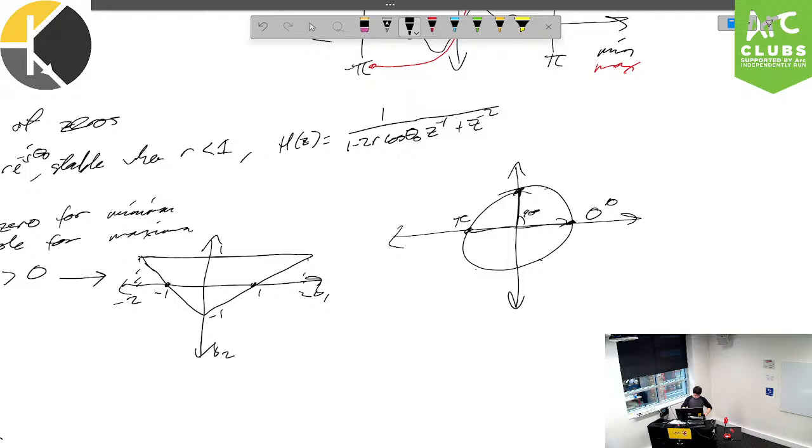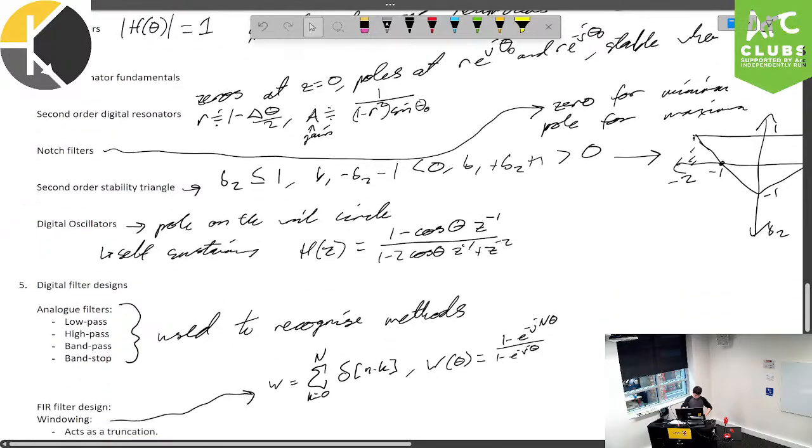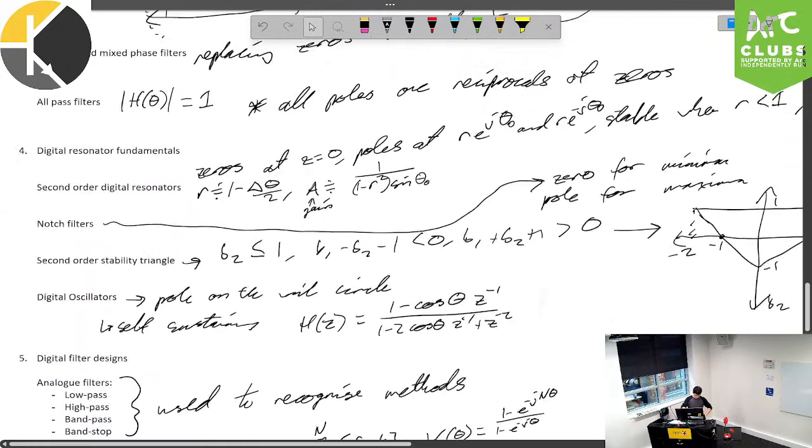And so, by having a 0 at 0, so I'll put an open circle there, by having 0 at 0, you effectively enforce a 0 action against all frequencies, if that makes sense. Because zeros try to pull it downwards, okay, to give you minimum. Whereas a pole tries to bring it up to infinity, okay? And that can be particularly seen in magnitude responses.